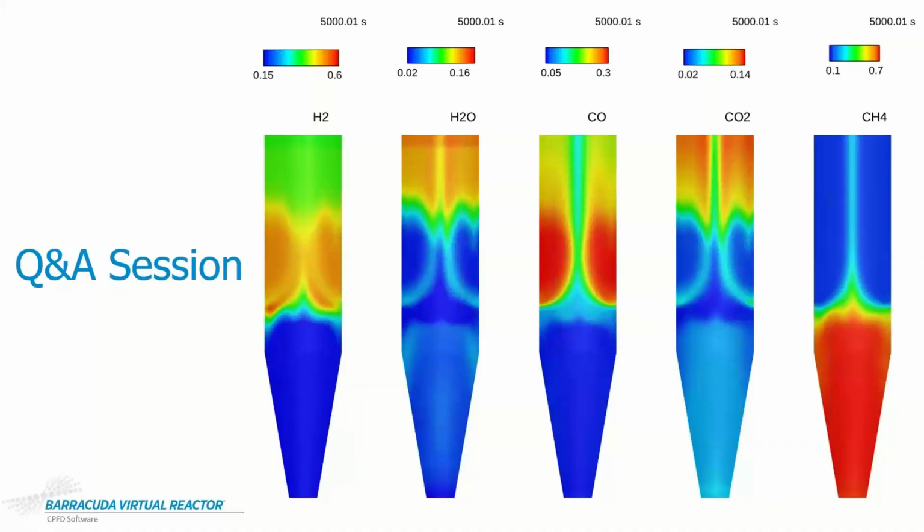Another question here, I think for you, Tanner. How did you initialize the solids as you say close to steady state? Yes, so the idea is, this model does have a fairly high residence time. So in Barracuda, we do need to have an initial condition or an initial distribution of solids. And we have the ability to choose what that might be.